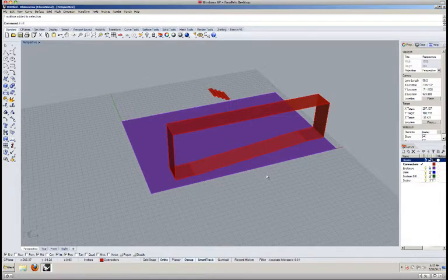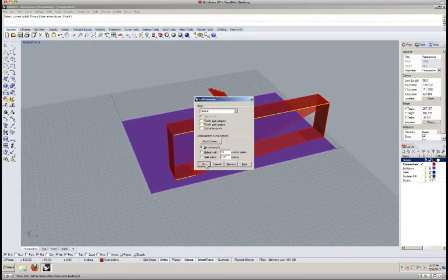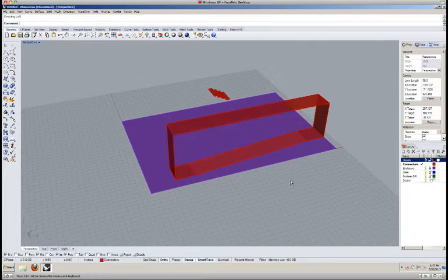So if we were to try to loft, and I tried to pick this and this, it's going to loft just those 2 portions together, right? So I'm not connecting to these others. If I try to loft all of the edges, so I'm going to click all 3 of these, and then I'm going to click the top one and hit enter, it's going to try to connect those in the way that I selected them, so that's not what we want either. So it might be easiest for us to duplicate these edges and join them together so that we have one polyline that we can loft with this top line. So there's a dupe edge command, and that allows for me to take a surface and pull an edge off of it. And I'm going to click all of these outside lines.